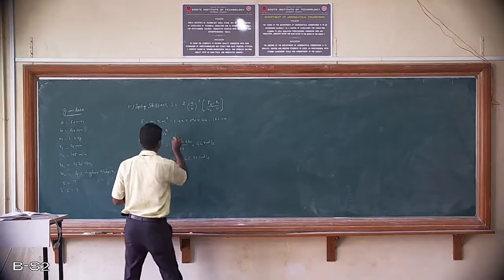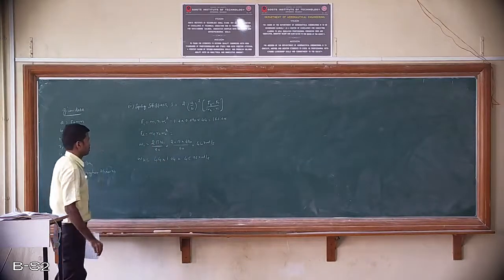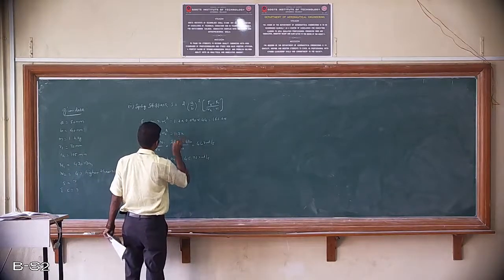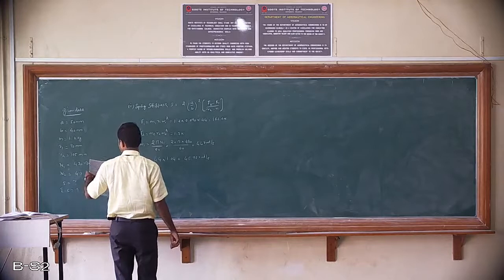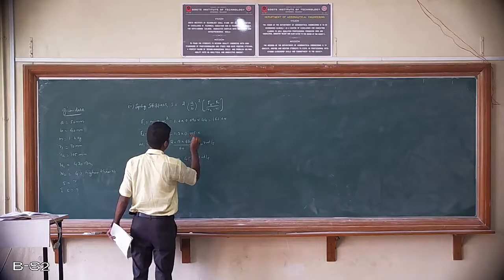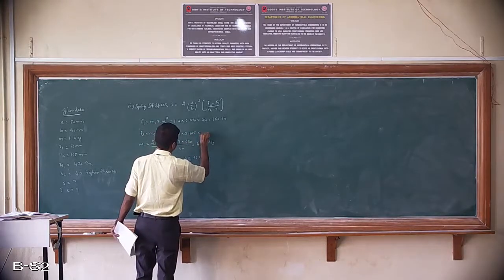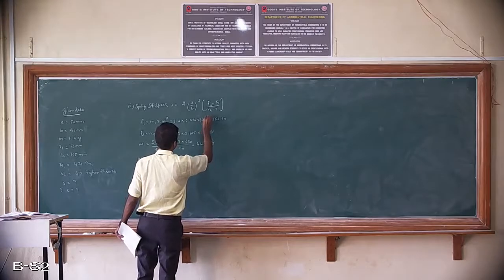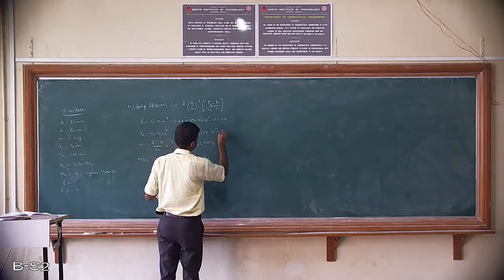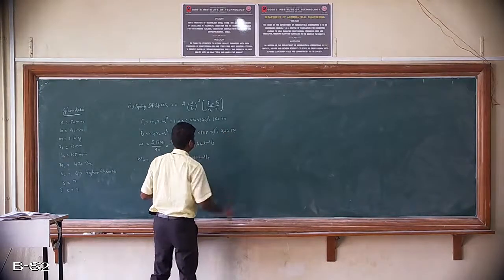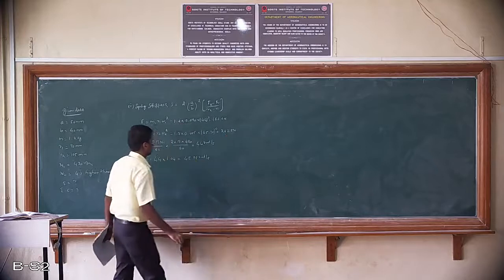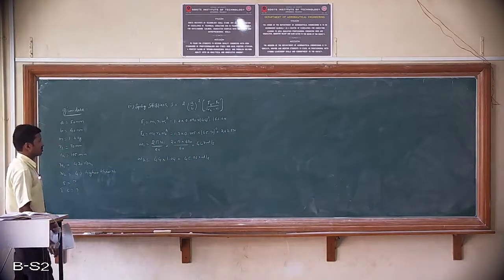Newton, and similarly calculate the value for F2, that is M2 R2 into omega 2 square. So M is constant, that is 1.2. R2 is 105 mm, so I need to substitute in terms of meters. So 0.105 multiplied with omega 2, which is 45.76, square. So this becomes the value of F2 as 263.8 Newton. So you got the value for F2 as 263.8 Newton.